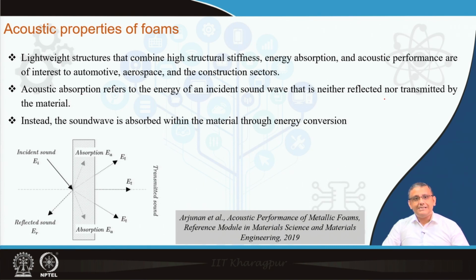And we learnt in the last lecture that many properties of the foams depend upon the type of the cell structure. As we know, foams can have either open cell or closed cell structure. And we learnt in the last lecture that if you want good thermal insulation, then closed cell foams are very attractive. Whereas, in applications where we need sound absorption, the open cell foams are more attractive,